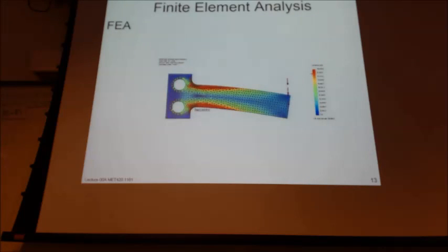So speaking of static, the other assumption that we'll make about things is that they are going to be linear and that they're in a static state. And why do we do mostly static? Well, because it's easy, cheaper, faster, and it can provide accurate results for what we're trying to solve. And when we talk about linearity, we're assuming that our material properties follow Hooke's law, right?